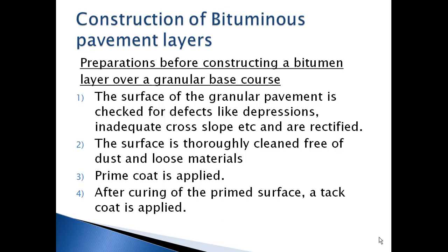The surface of the base course is checked for any defects, like if there are any depressions or holes, they are filled in. And if there is a change in the slope, if the cross slope is not maintained properly, then adequate slope is maintained and all the defects are rectified.